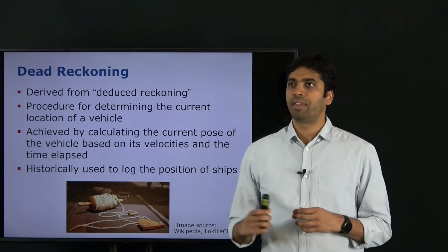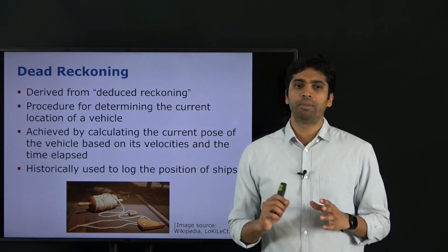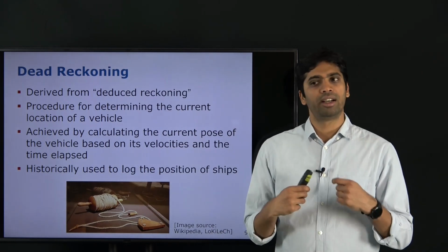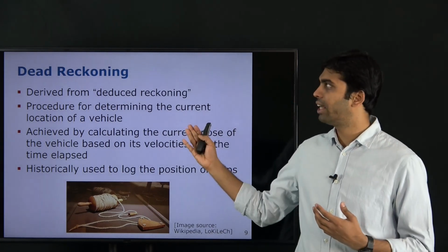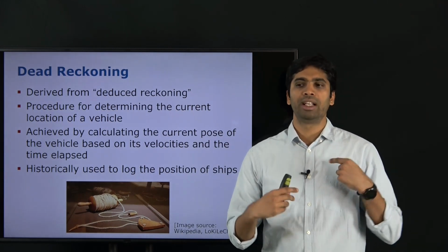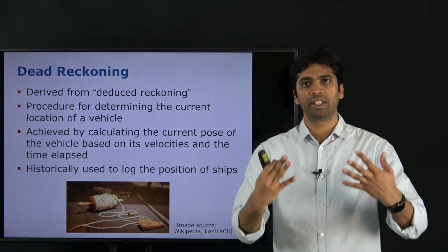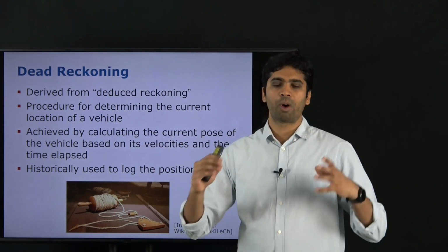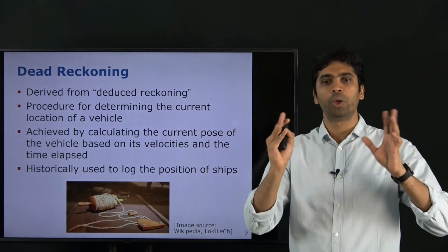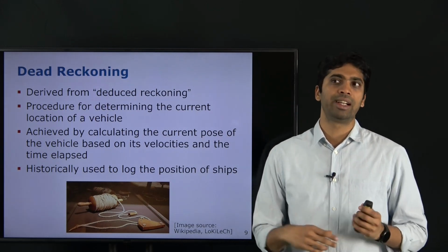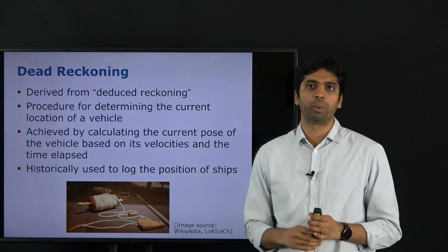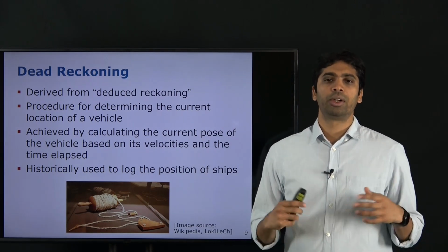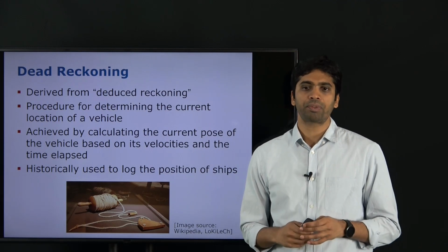In practice, the odometry model often gives better or higher accuracy measurements than dead reckoning, because the odometry model captures the rotations after the command has been executed, whereas in the dead reckoning model you just hope that this particular command is executed, but you actually don't know what happened in between. So in practice, we often use the odometry model for the motion.